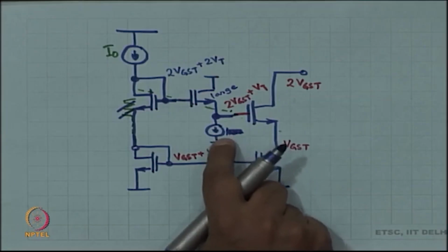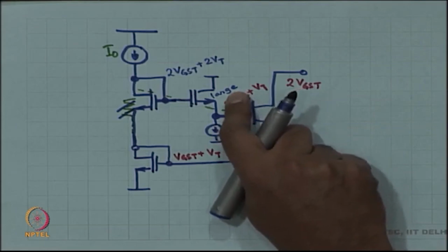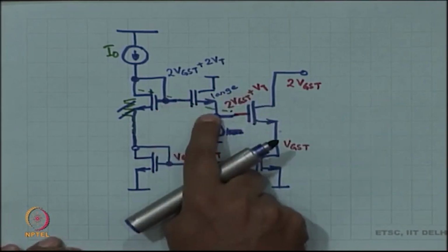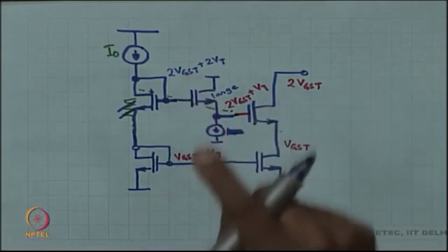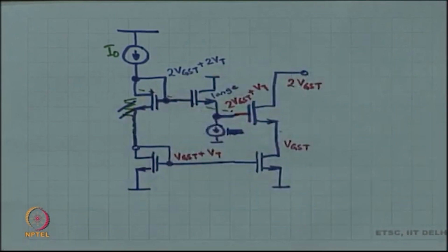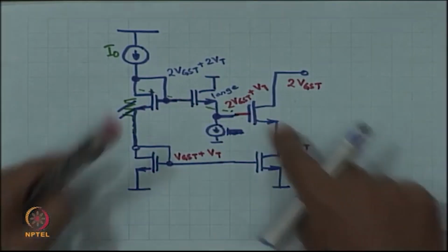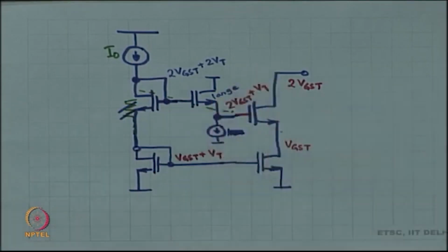Okay. So, if I push a small current through a large MOSFET, then the VGST required is going to be minimal, almost equal to 0, in which case I will just get a VT drop. All that I now have to do is pull a current through this very large MOSFET. So, you may take a very large MOSFET, W by L is very large as opposed to these 4 having equal W by L. Over here you pick W by L to be very, very large.